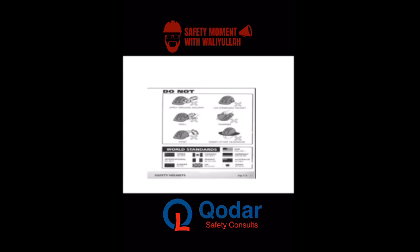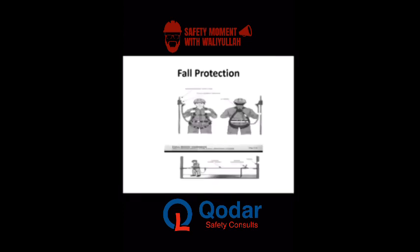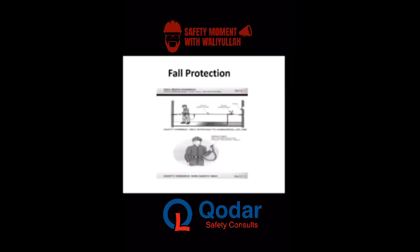This is a helmet. We want to make sure that it is always kept in good condition. This is fall protection when walking at height. This is a harness belt that needs to be worn. Sometimes workers will say, I've been working for years. Working for years is not a guarantee that when an accident wants to happen, it will not happen to you. So we do not want to accept any form of compromise. This harness fall protection must be worn at all times. A full body harness must be worn.